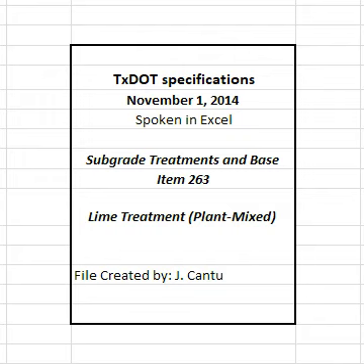4.3.1 Ordinary compaction. Roll with approved compaction equipment as directed. Correct irregularities, depressions, and weak spots immediately by scarifying the areas affected, adding or removing treated material as required, reshaping, and recompacting.